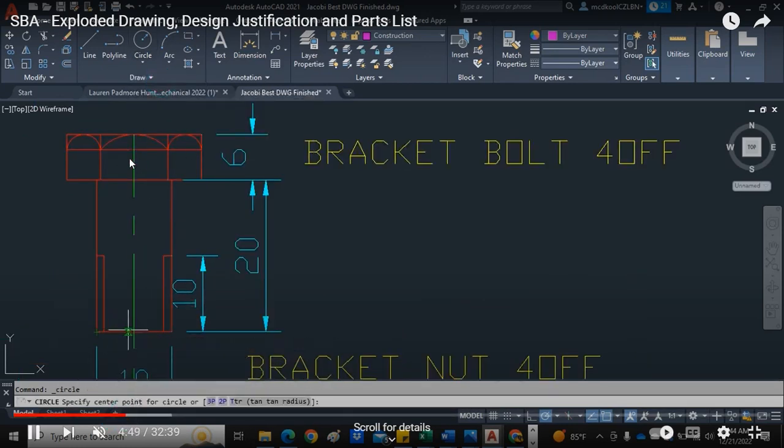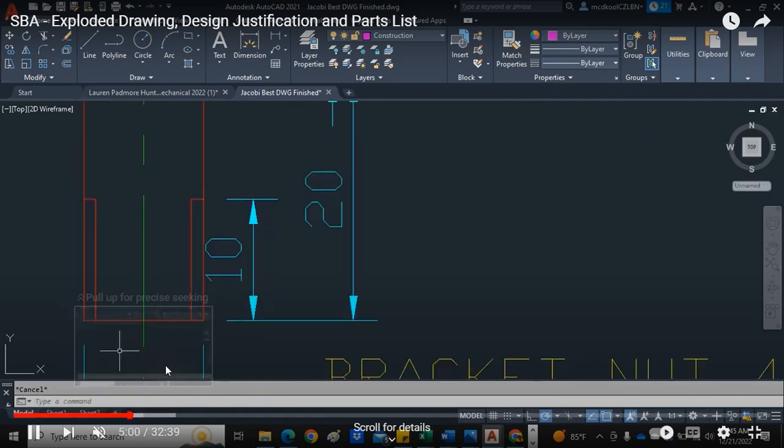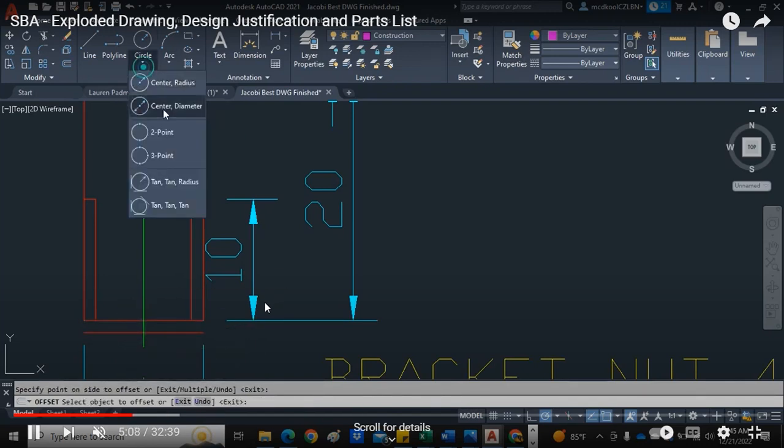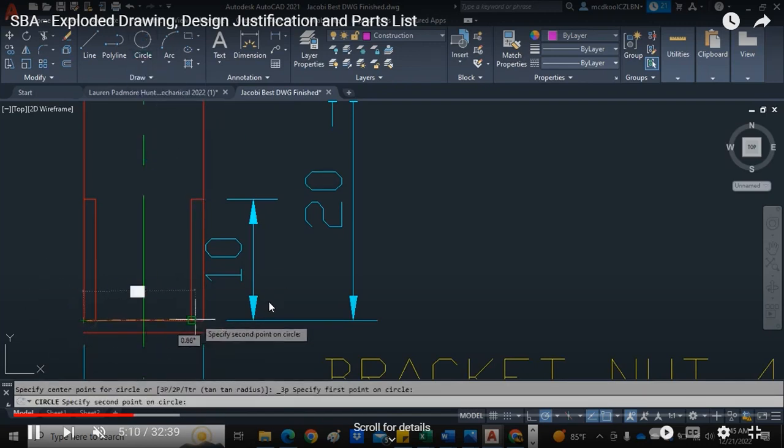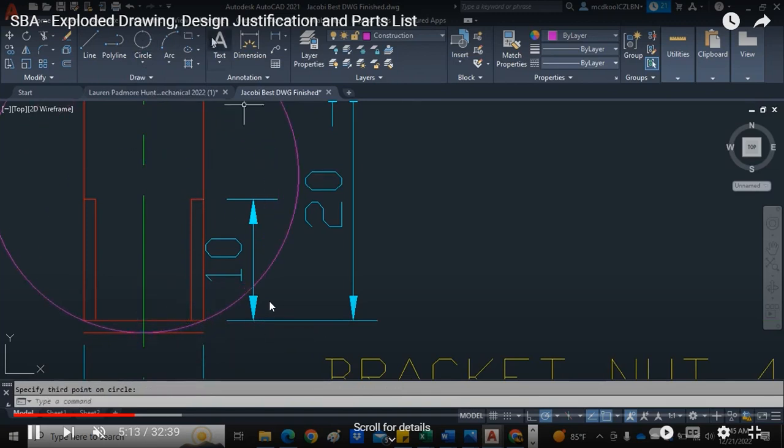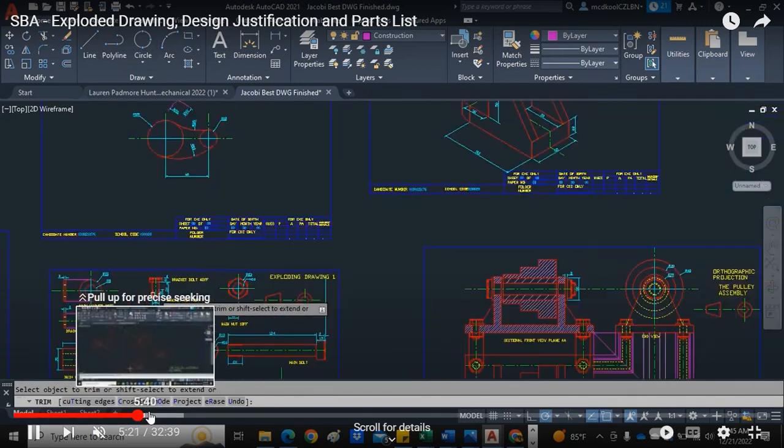Over here, it is good, the person has the bumps, but the issue with this was this student did not put in the curve that was here at the bottom. So to get that curve in, you offset just by 1 millimeter or so. Pull down your line, and then we use a 3-point curve. Left to the right, and put in your 3-point, and that gives us a smooth curve. And you can just trim off and change the layer.